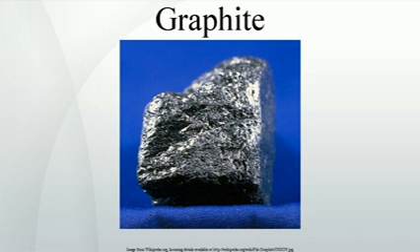Refractories. This end use begins before 1900 with the graphite crucible used to hold molten metal. This is now a minor part of refractories. In the mid-1980s, the carbon magnesite brick became important, and a bit later the alumina graphite shape. Currently the order of importance is alumina graphite shapes, carbon magnesite brick, monolithics, gunning and ramming mixes, and then crucibles. Crucibles began using very large flake graphite, and carbon magnesite brick requiring not quite so large flake graphite. For these and others there is now much more flexibility in size of flake required, and amorphous graphite is no longer restricted to low-end refractories.